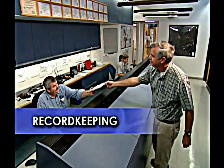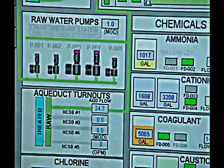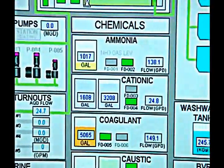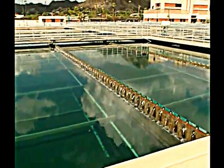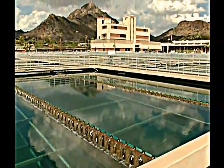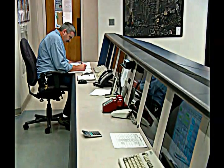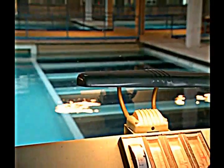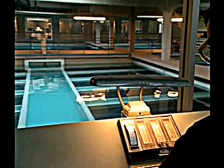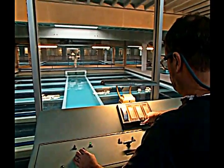Throughout the process, the operator should keep detailed records. It's important to note the changing raw water quality and chemical doses that worked effectively. Record seasonal changes and factors such as heavy rains, snowmelt, and drought conditions. Record keeping is one of the steps operators can take to make sure they are optimizing their coagulation, flocculation, and sedimentation techniques. Optimization can be achieved through additional operator training and ongoing evaluation of equipment and techniques.